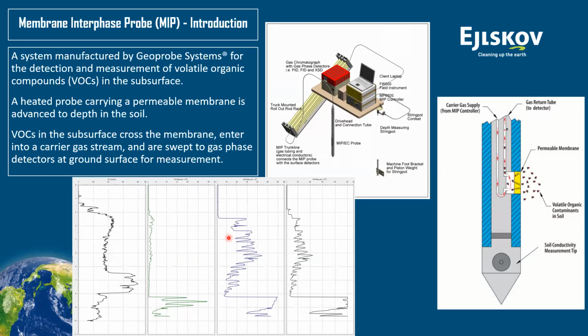But most importantly, you collect high resolution qualitative data as you go through your subsurface by heating up the soil, desorbing the contamination that may or may not be present in the formation around your probe. That contamination will enter a semi-permeable membrane placed on the heated probe, and then a carrier gas will carry that gas stream over to the mass detector and the instrument that we have in the field, so that you can get a signal of how much contamination you may have at different depths.